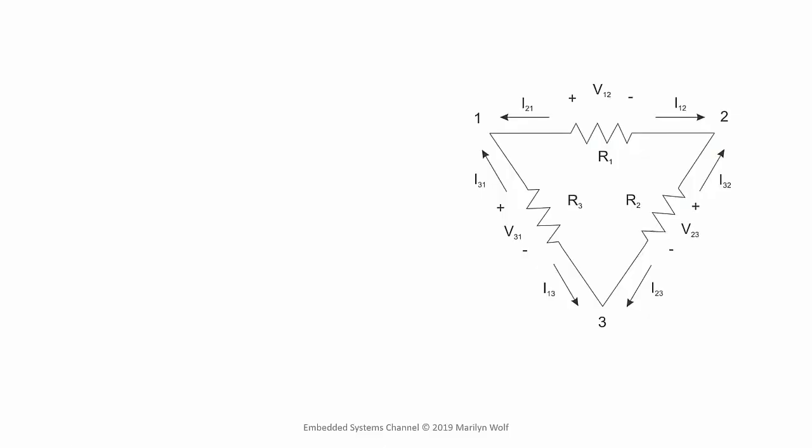Several physical and mathematical laws guide our design of circuits. Here's a simple, perhaps unusual example of a circuit that we can use to illustrate some important laws. Kirchhoff's voltage law says that around any loop in the circuit, the sum of all the voltages is equal to 0. This depends, of course, upon us properly defining the polarities of the voltages. But with properly defined voltages, for example, the sum of the 3 voltages across the 3 resistors in this circuit is equal to 0.